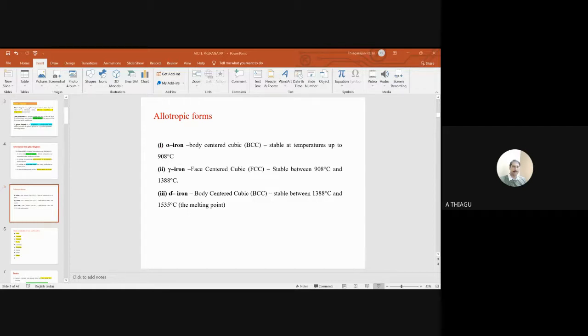Now you look at this. This is the point A and B. I am taking the sample of 0.8 percent carbon. The sample should be heated at 750 degrees for 3 hours. Now at this point you can look at the entire microstructure. The entire microstructure should be in the form of austenite. You can look at the phase, it is entirely austenite material.